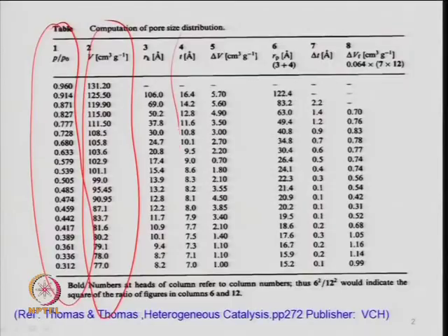But if you want to get the in-depth pore analysis, pore size distribution, you need to look at the t-plot. So, you need to find out the adsorbed layer thickness, which we talked about last time, based on Wheeler's model, and the Kelvin radius. That also we talked about in terms of the vapor pressure relation or Kelvin equation.